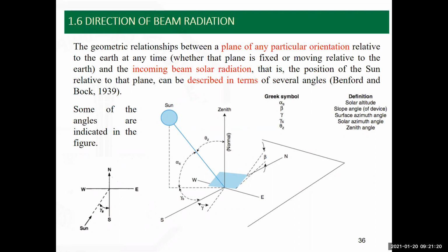Because the amount of energy which is falling from the sun is dependent on that. The solar energy becomes more if it is directly normal to a certain surface. How to make it normal to a surface? You try to tilt it from the ground and change it so that it would face south or east. Why is that? Because we need to make use of as much solar energy falling as possible.